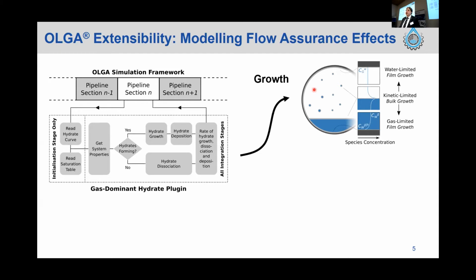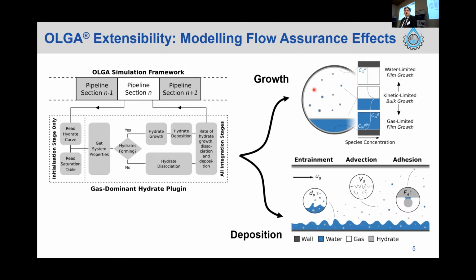So these are entrained droplets that are picked up by the gas phase moving over the liquid and transported and converted. So the question is, what happens to these droplets in particular? Once they're entrained, they can either be advected along the pipeline, they can fall back into the liquid and be carried along in that slurry phase, or they can wind up sticking to the walls, and then they will form a deposit, as we saw in the previous slide there.